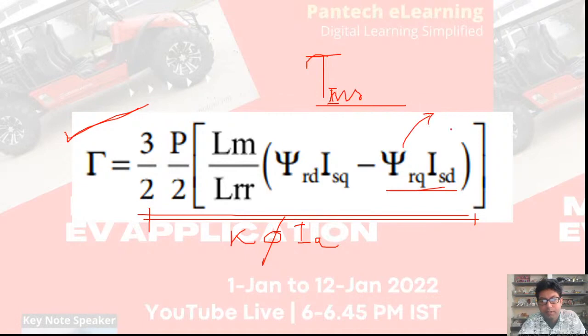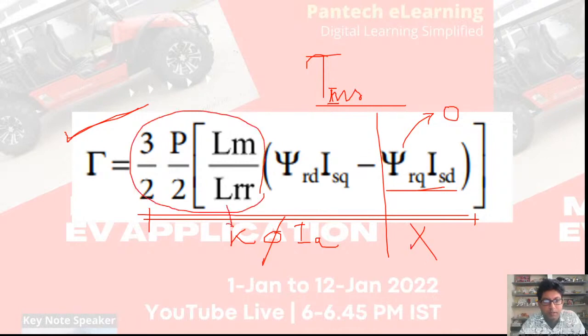Using some control technique, I have to make this flux 0. If I make it 0, this part will be cancelled and this entire part will be treated as a constant, and this psi RD is the field flux and the stator quadrature axis current is nothing but the armature current. So we will slowly learn how, by adopting some control technique, to make that psi RQ 0.